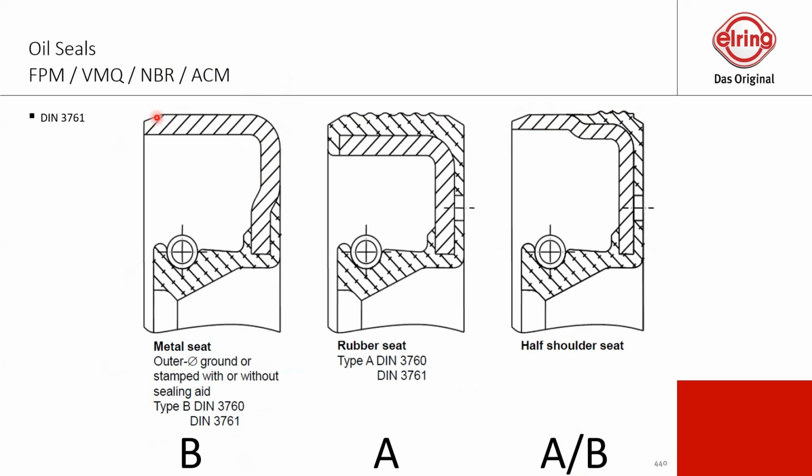The reason is quite easy, because the fitting into a housing is close, with fewer gaps in between. This is pressed in. These are applications like gas, water, whatever. So what is very thin, what can best pass by. We have applications where we want to seal against oil, and against any dust. And there's quite a good solution for it. It's metal and rubber, or only rubber, depending on the tolerances and also the pressure that it works under on that kind of spot.